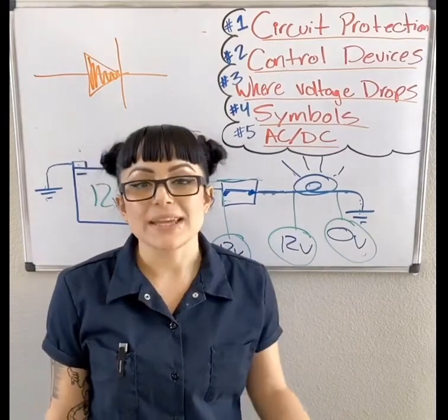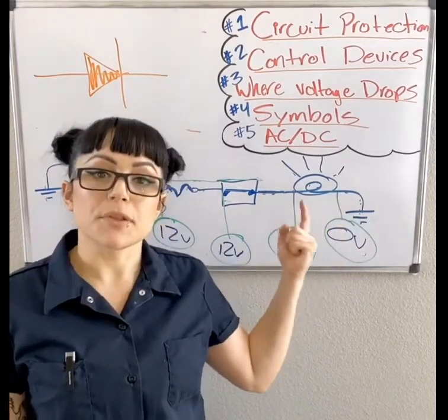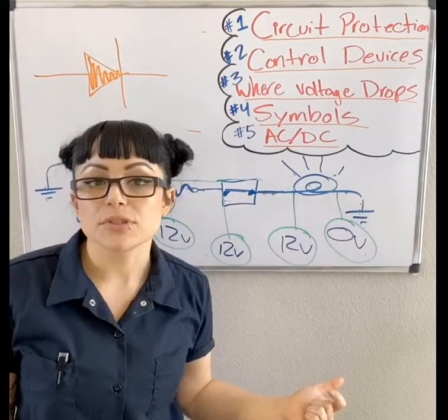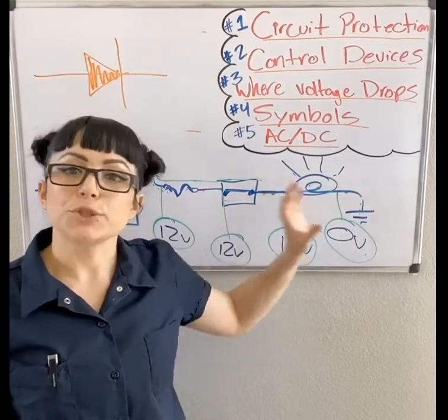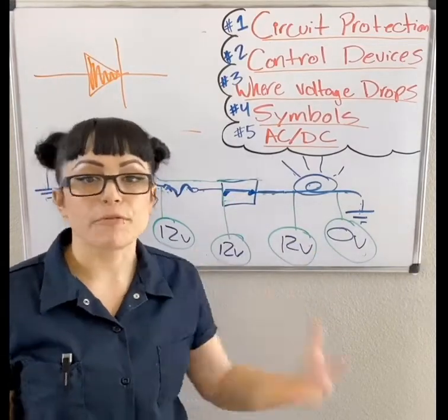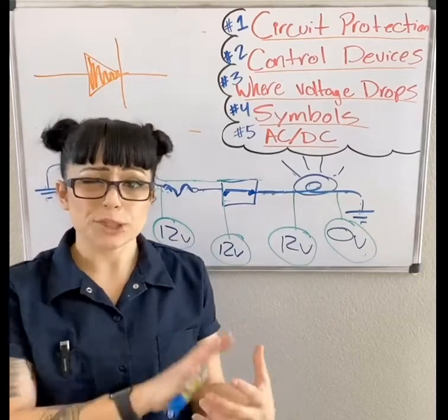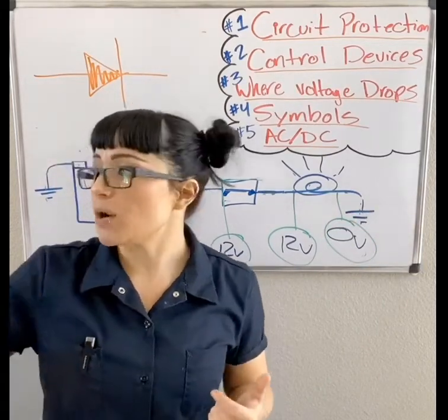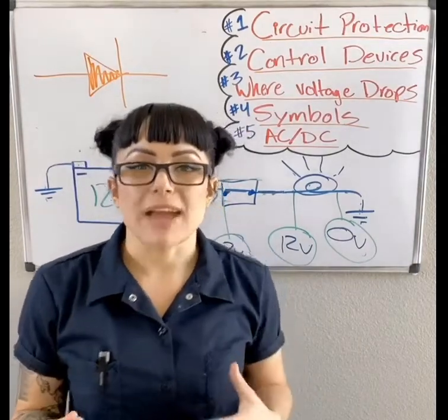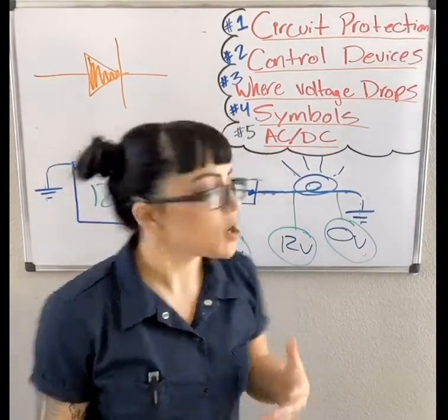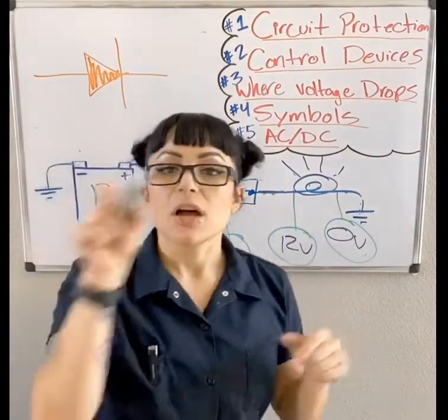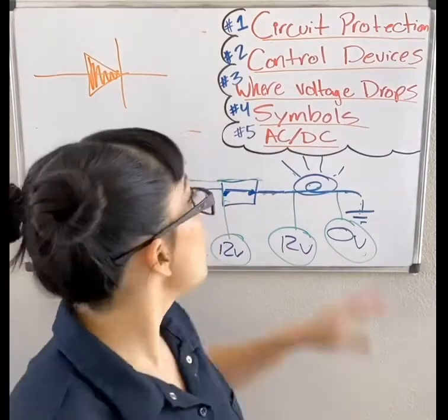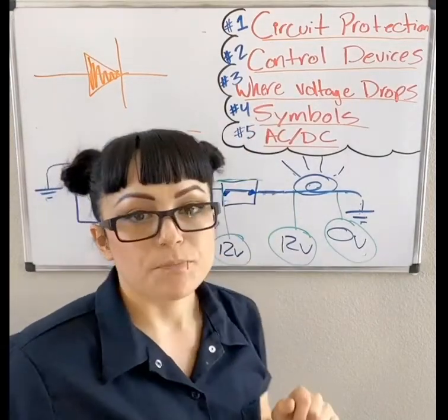So what will happen is I have pressure coming up to the light bulb, but if I don't have, let's say, connection to chassis ground, I have no continuity. That pressure is an empty pressure, and I have no current flow behind that pressure for it to push. I can't really have real pressure, let's say in a water system, without the water, right? It would be an empty pressure. So it's important that we have continuity, or a path for continuous flow. So that would be where voltage should drop and where it should not.